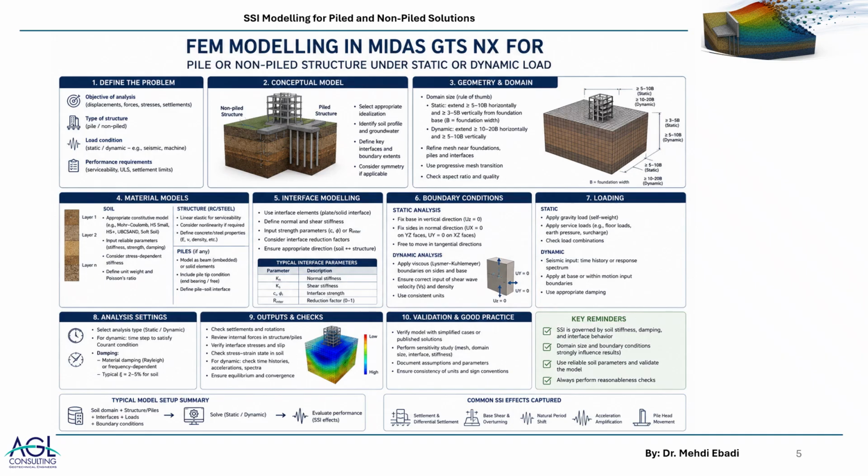The other major category is that they ask us to do analysis for obtaining the settlements and deformations of the structure and the angular distortions, and then we provide those values so that they check those values against the tolerable thresholds of their structure.